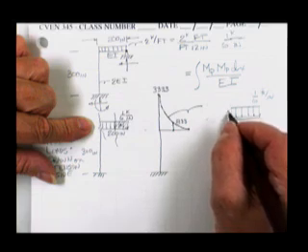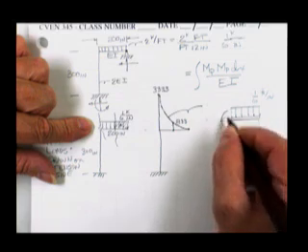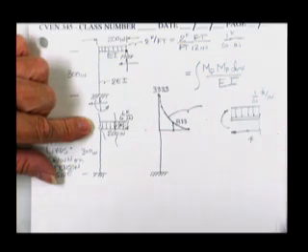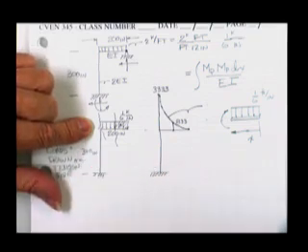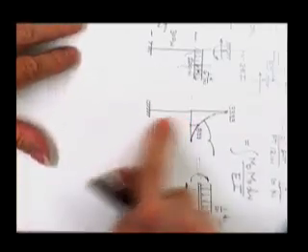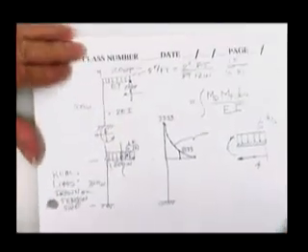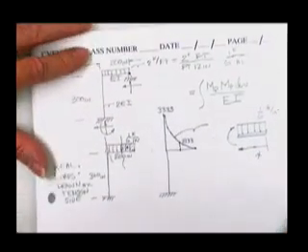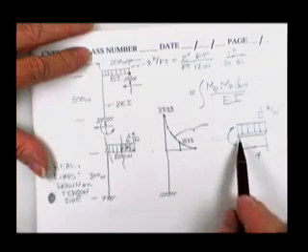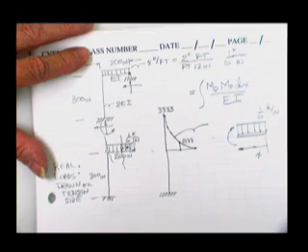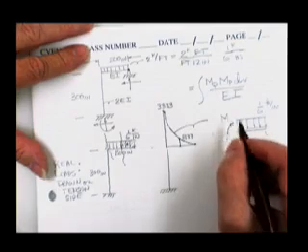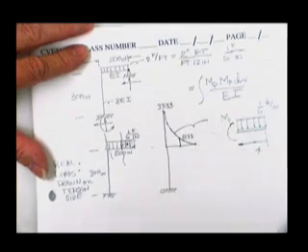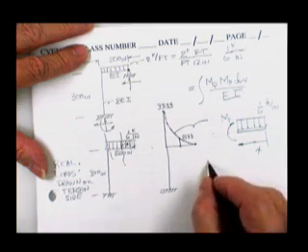There is a bending moment on the beam. I highly suggest you always put the unknown moment in the positive direction on the beam. I don't know exactly what to tell you once we turn this thing this way to get this beam, but it probably makes sense to show the moment in the positive direction, and if the moment equation comes out minus, then you just say it's a minus. Here's the moment due to the real loads.